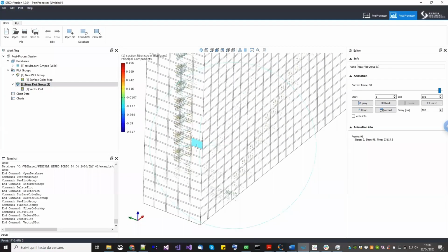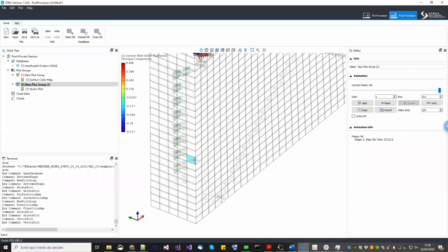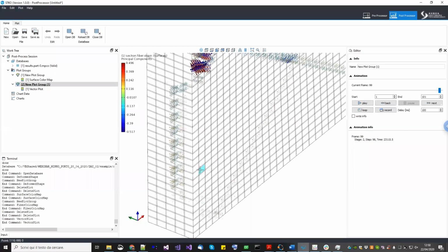Now in this case, this is possible because our constitutive model is 3D, and the shell that we are using is a thick shell. So a thick shell has treatment for the transverse shear. The transverse shear goes to the material model, and the material model can handle it in a nonlinear fashion.